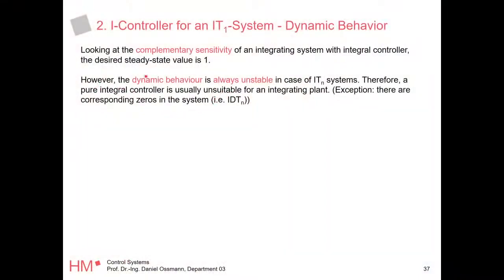So the dynamic behavior for an integral system without differentiating elements, right? So it might be different if you have additional D terms in there. But if you just have ITN systems and you plug in an integrator, it's always going to be unstable. You cannot stabilize, or differently said, you cannot have two integrators in your system if the system is pure integrating and delayed. You'll see that in a second.